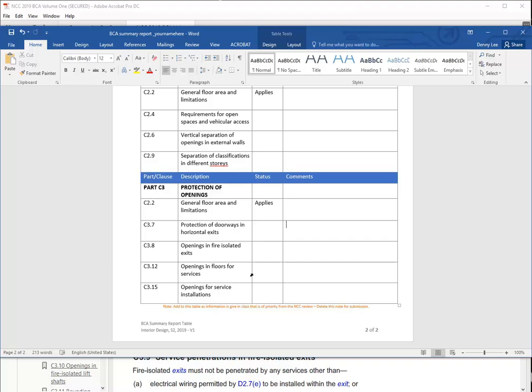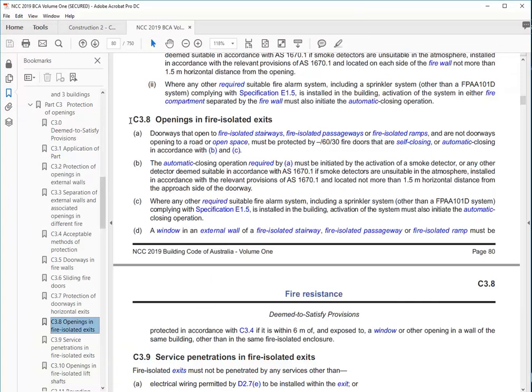Yeah, they should, of course. Always. I mean, look, I've done a 25-storey apartment building and all the doors still open into the apartment. They don't open out. But people make a mistake and think they all have to open the other way. Because it does say in some cases they do, but not in all cases. So it's good information. You should be reading this. I think it's actually interesting if you want to be designing buildings.